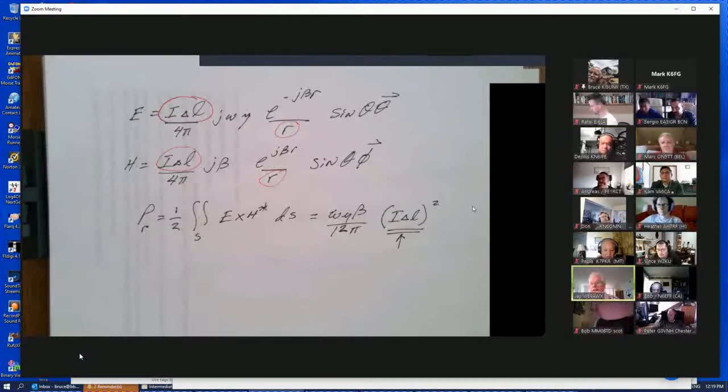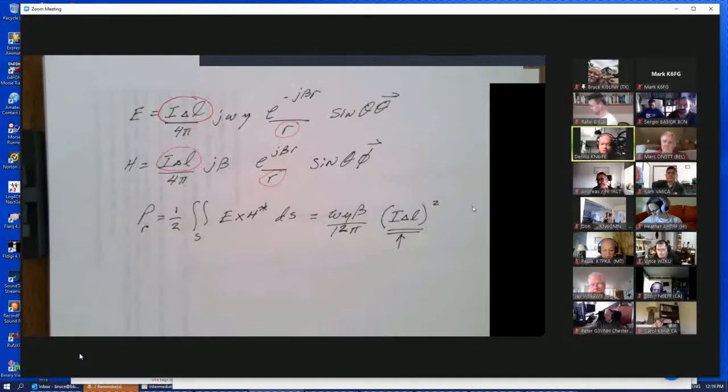Well, how are you matching it? I'm using an air variable capacitor. Okay, so you match basically. Secondly, I minimized the length of the transmission line, the coax to the antenna. Well, transmission line is proper, yeah.